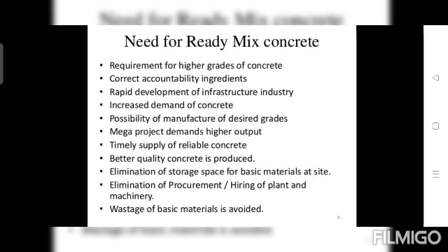Sometimes they are placing mass concrete like bridges and dams, which requires bulk quantity of concrete, and at that time hand mixing and mechanical machine mixing are not comfortable. In those situations we use ready mix concrete.